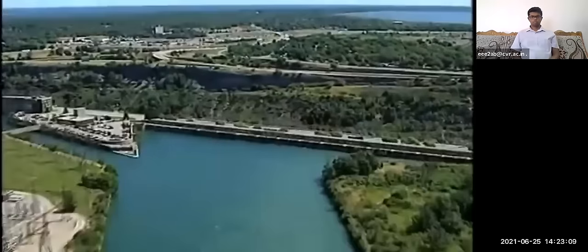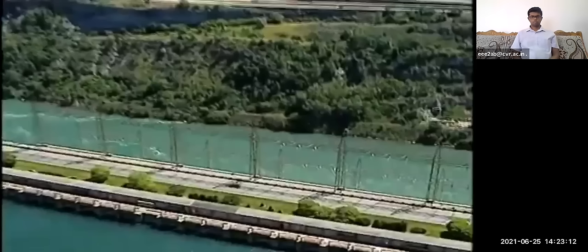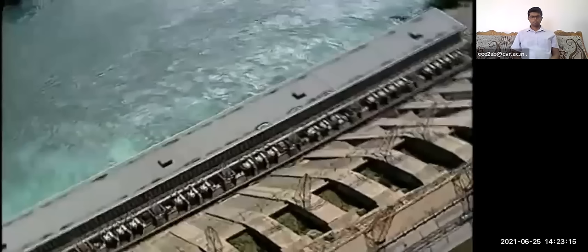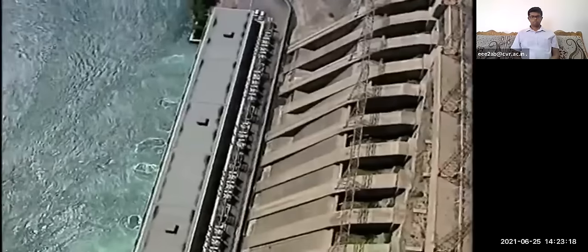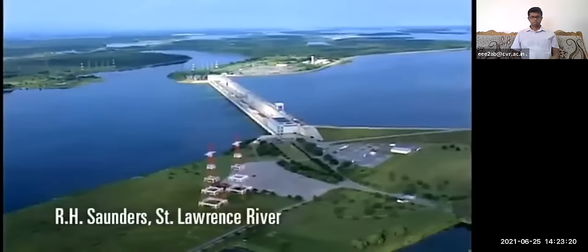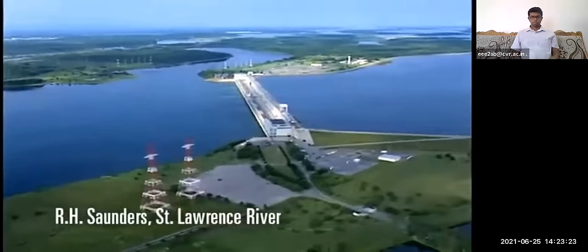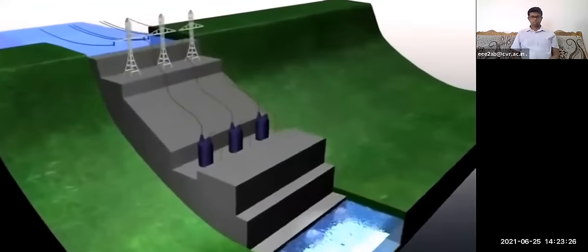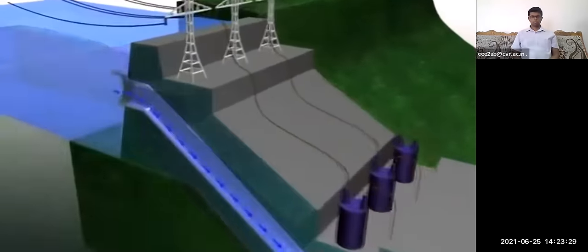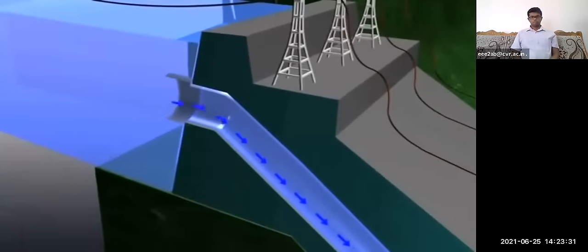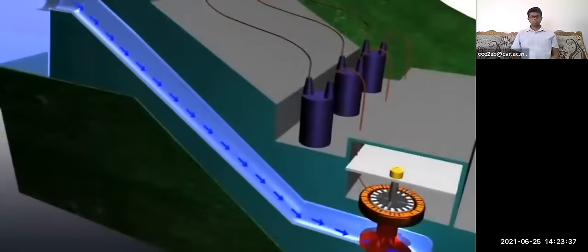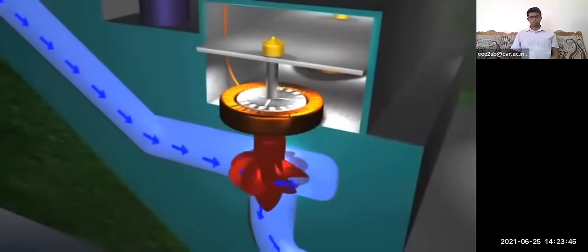Most hydroelectric stations use either water diverted around the natural drop of a river, such as a waterfall or rapids, or a dam is built across a river to raise the water level and provide the drop needed to create a driving force. Water at the higher level is collected in the forebay. It flows through the plant intake into a pipe called a penstock, which carries it down to a turbine water wheel at the lower water level. The water pressure increases as it flows down the penstock. It is this pressure and flow that drives the turbine that is connected to the generator.